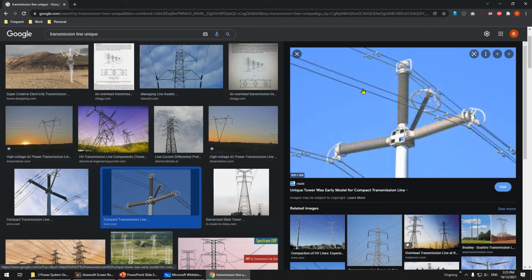Okay, you can see here this is bare wire. Usually we can see that the wire has insulation, right, normally, but for transmission line it doesn't have any insulation. This is the wire. Basically why? Because we want to ease the heat dissipation. Remember P loss equals I squared R. The power loss is in the form of heat, and we want to ease the dissipation. Also insulation is quite heavy, so you want to reduce the weight.